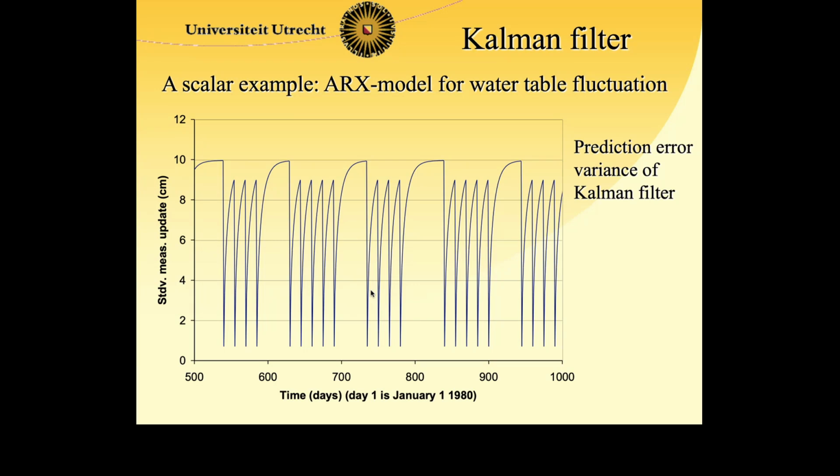What actually is interesting is if we now start to compare how this variance, how this uncertainty develops over time. This so-called sawtooth can be described by seeing how this error accumulates over time if you don't do any update.